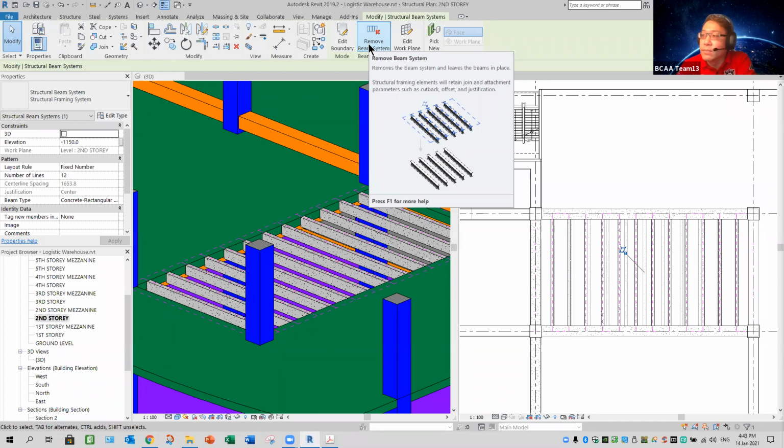Things that you create as a group, as a system, the Revit engine will keep monitoring any changes, any updates. So when things are finalized, don't keep it as a system anymore because it's just to simplify for editing. If there's no change, then why you want to sacrifice that process doing nothing just waiting for information?